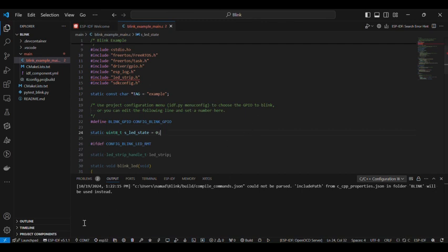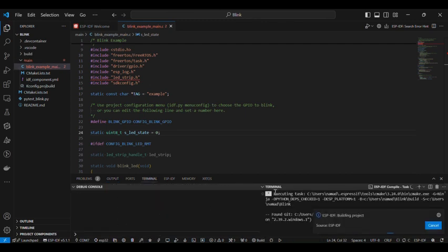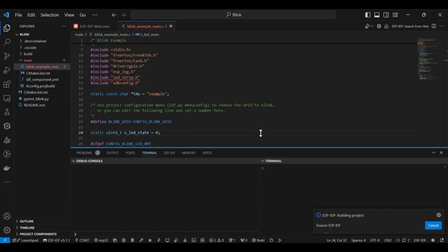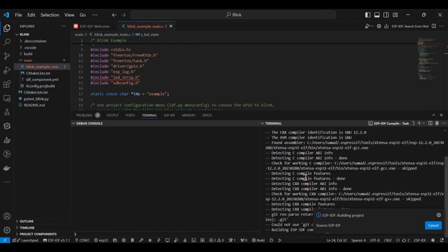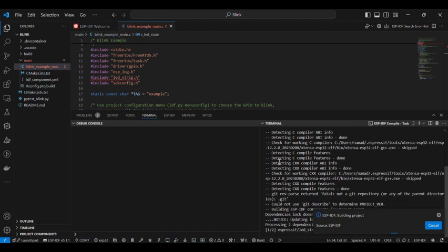to run that you can see there are options here. This is the ESP IDF version and this is the COM port. This is for ESP32. Then you should find the ESP IDF build project. If you press it, it will try to build here. It will take time to run the project the first time. So let's wait.